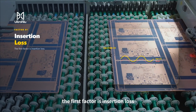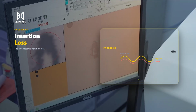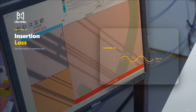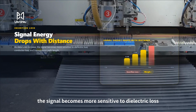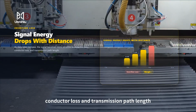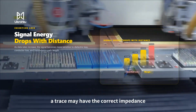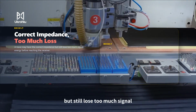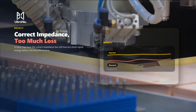The first factor is insertion loss. As data rates increase, the signal becomes more sensitive to dielectric loss, conductor loss, and transmission path length. A trace may have the correct impedance but still lose too much signal energy before reaching the receiver.